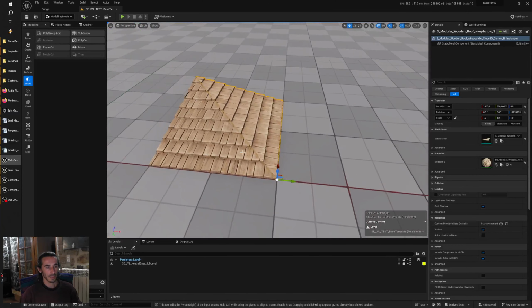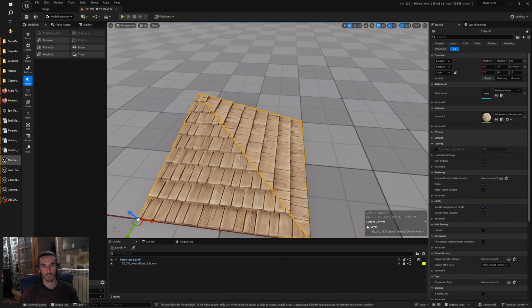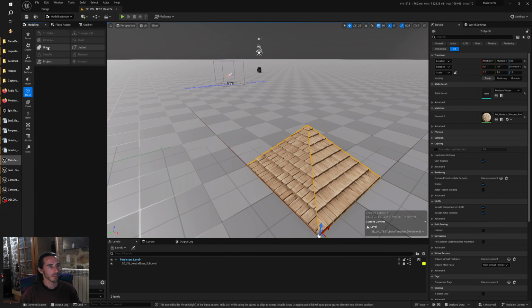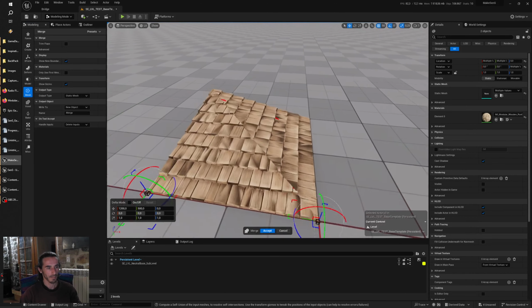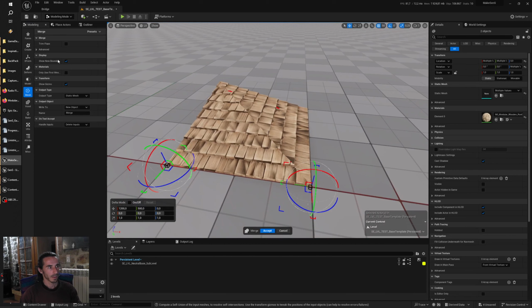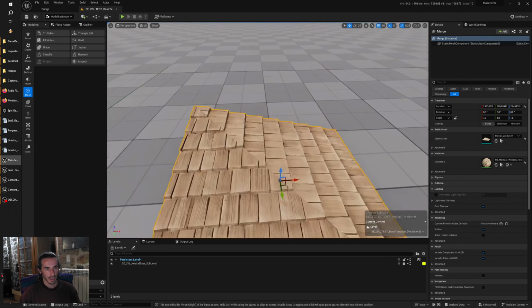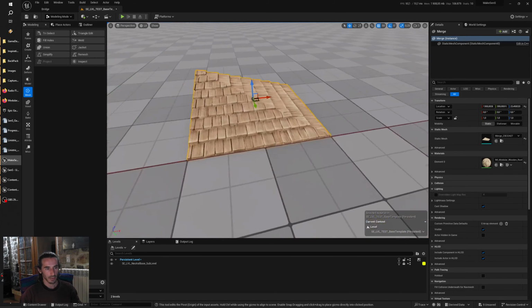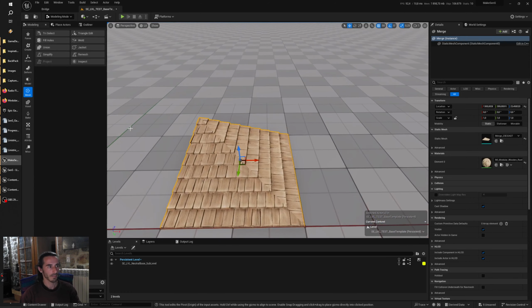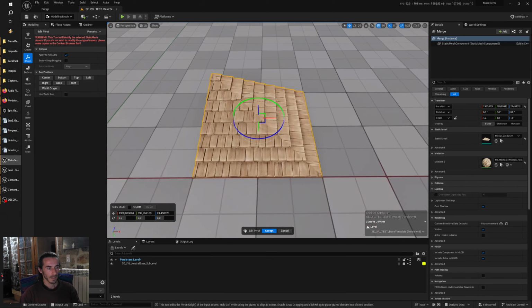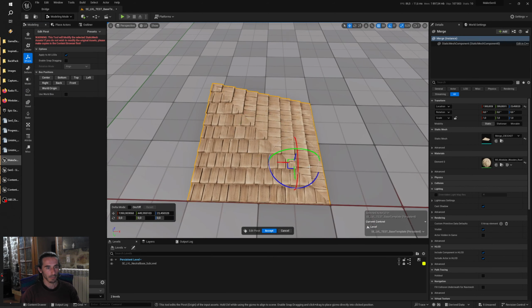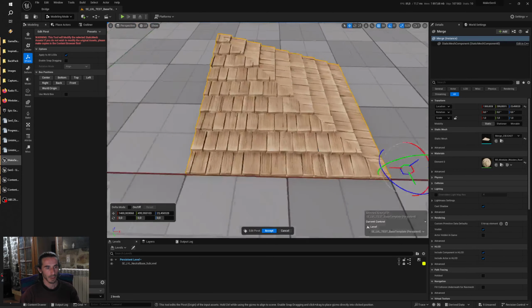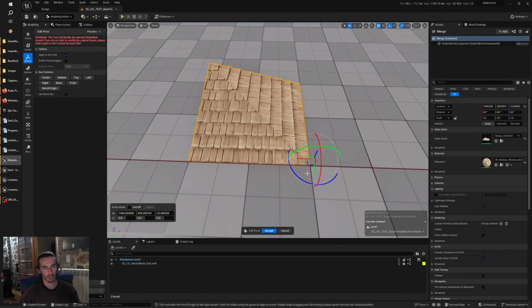So now the last operation is to merge these models. Mesh union. Okay. The options are good. The name is merge. Okay, fine. Accept. And you can see the pivot point is on the center. This is not convenient. So we have to move it. We are going to move it here or here, as you prefer.